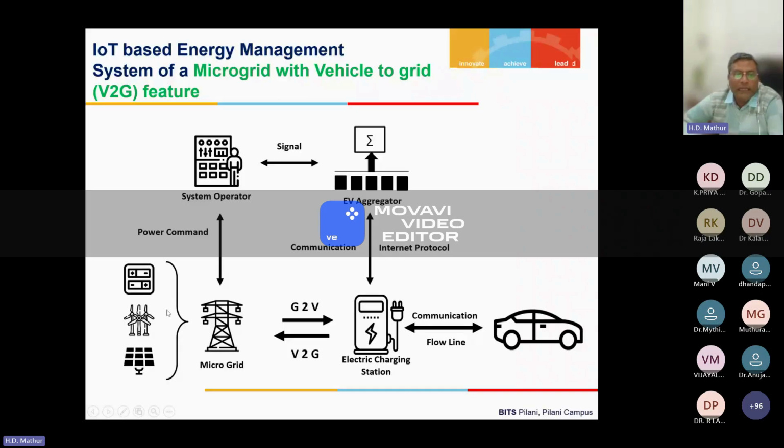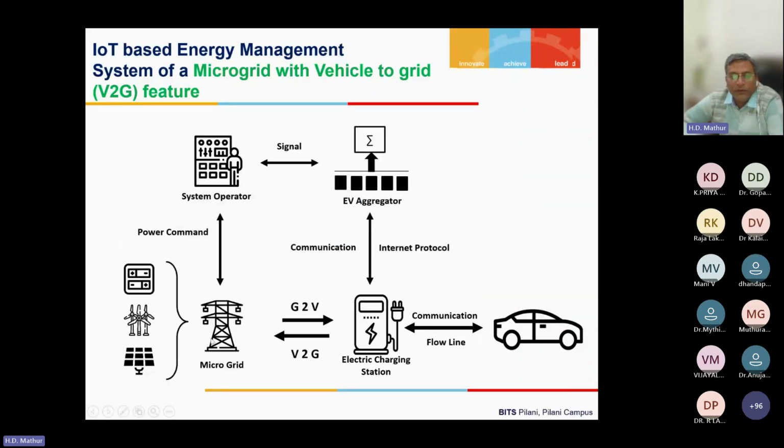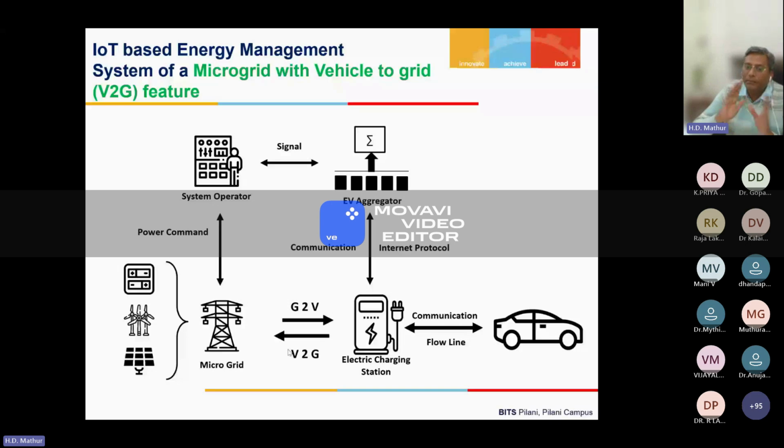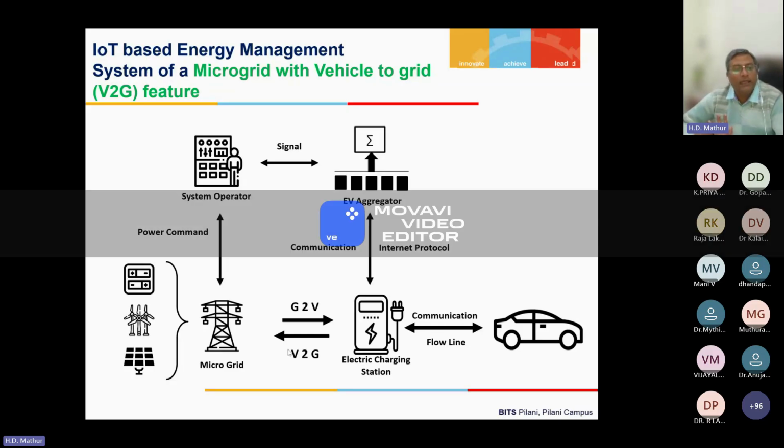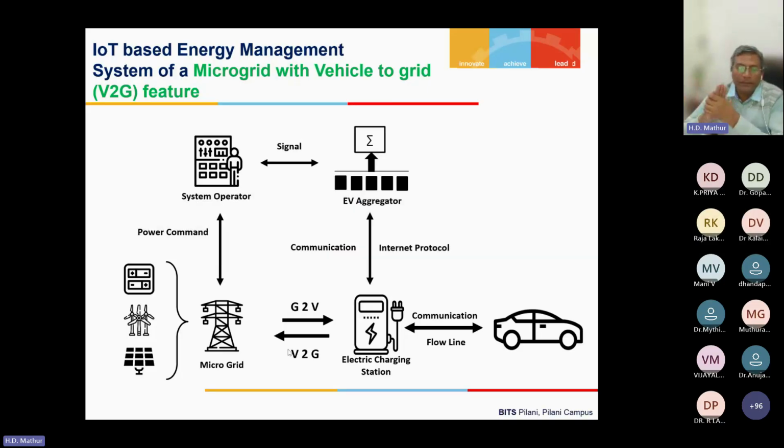And what have we developed on our campus? We have developed a microgrid with solar-based charging, and since we get data on a real-time basis every 5 minutes, we implemented our own LSTM-based algorithm, and we are able to predict what is going to happen tomorrow. That prediction has helped us in saving electrical power. The saving is from the solar panel, because we don't take any power from the grid. During night time, because this is installed within our campus, where there is a supermarket that works from 9 a.m. to 8 p.m., from 5 to 8 it runs on the battery energy storage system, right?